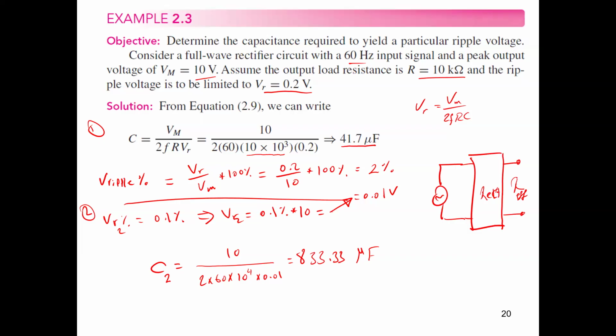How can we do that? You can use any circuit analysis technique, definitely Thevenin analysis. Once you get the output current and the voltage here, you can get R effective as V output divided by I output. So this is going to be your effective resistance, and in this way, you can make sizing for your capacitor.